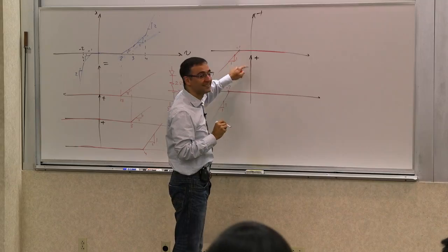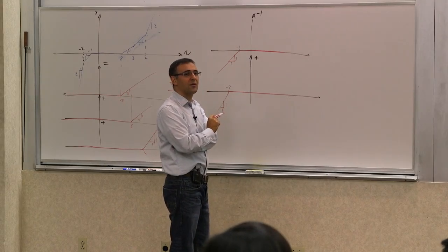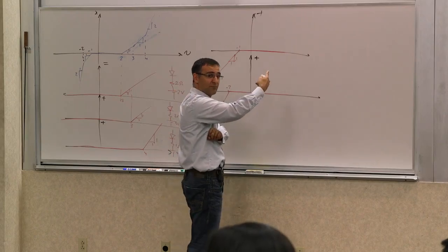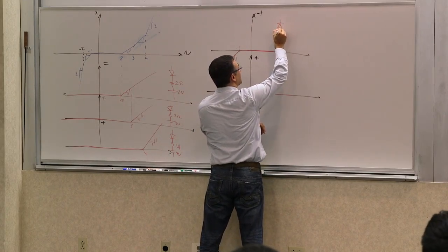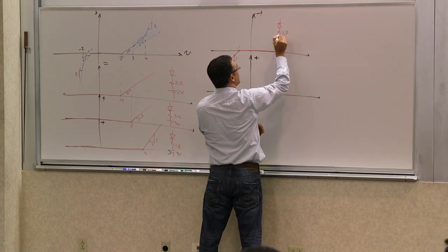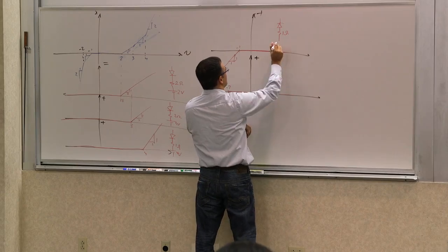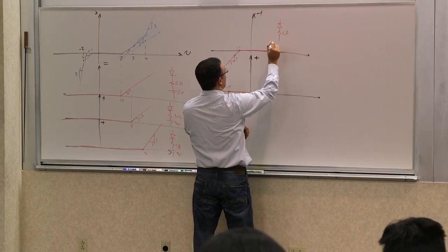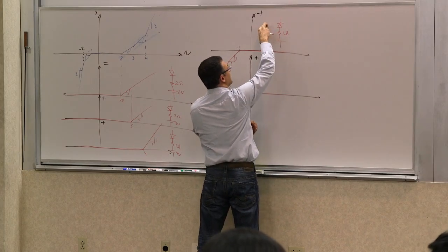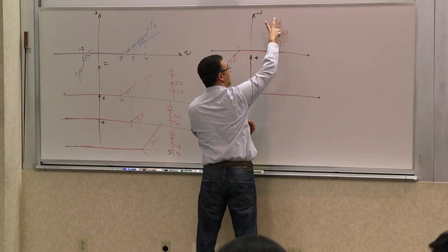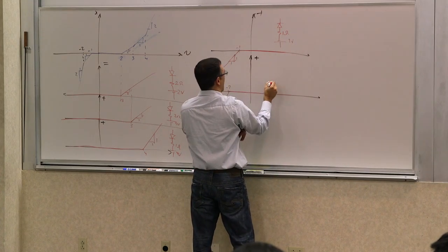How do you generate that? The same diode, the same way? No, reverse. Yeah, I have to flip it because now it's creating the opposite. So now the diode has to be this way, and a resistor of 1 ohm. 1 volt in which direction? Right, because when this voltage becomes 0, basically you need to have a -1 here across this, which is cancelled by that. So this is going to be 1 volt. And then how about the last one?